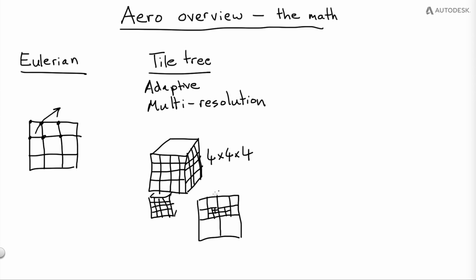So we do the same thing, except instead of always splitting by 2, we can split by a user-defined parameter. In the liquid solver, we tend to split by 5. In the Aero solver, we often just split by 2. And then instead of just having a single grid cell here, we actually use tiles. So we have a very efficient, performant data structure to capture all of this.